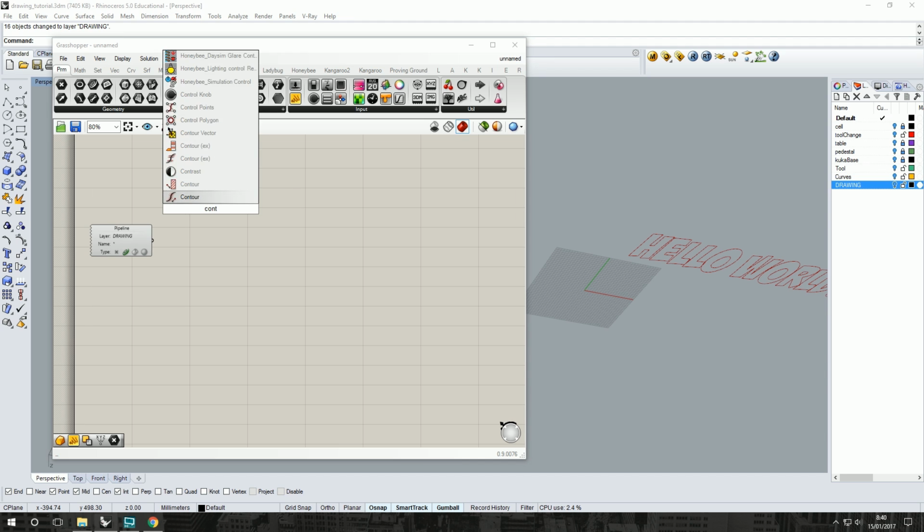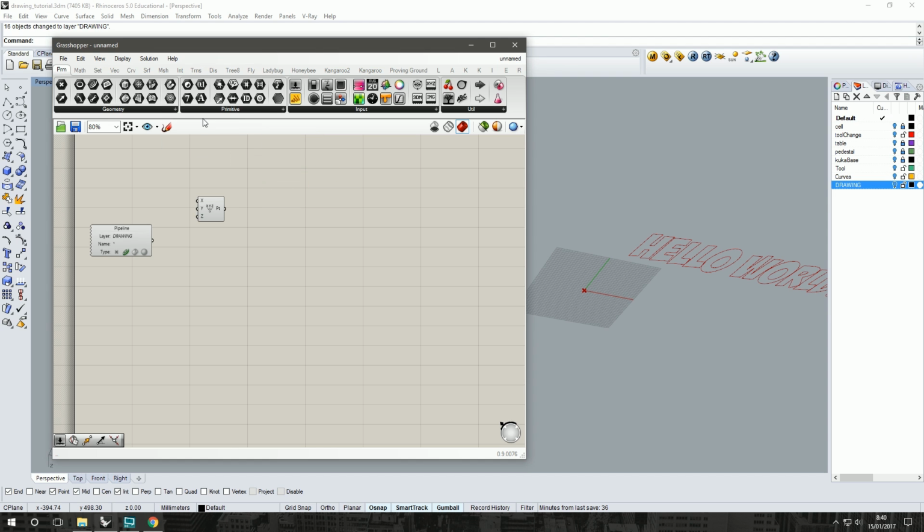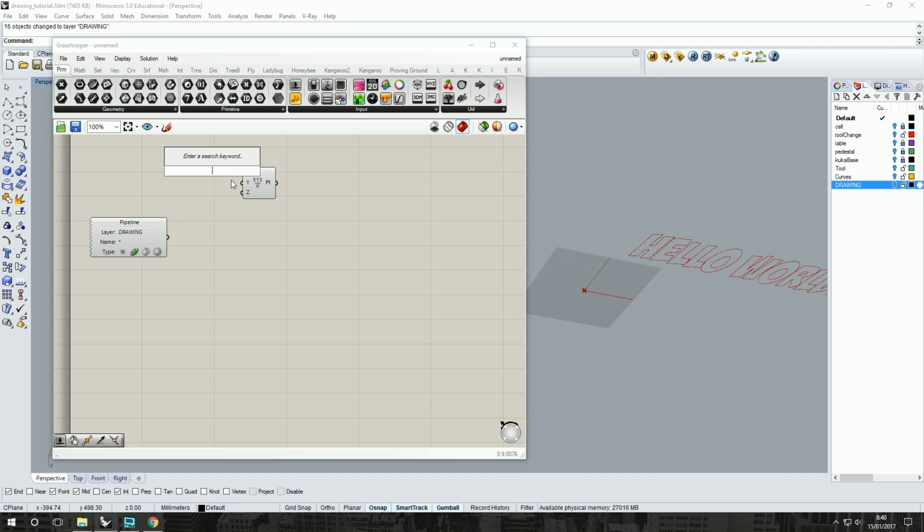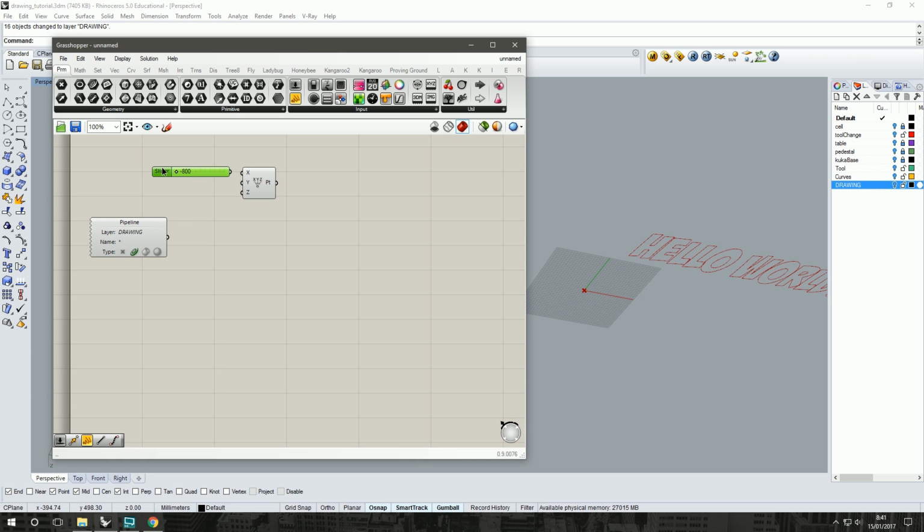So for this, we're going to construct 3 points. Construct point. We will put on, let's see, we will be going from to 1800. So we know we've got a relatively large canvas size. We'll duplicate that just by clicking, dragging, and then holding down Alt. Allows us to duplicate any component. Put them into our construct point.